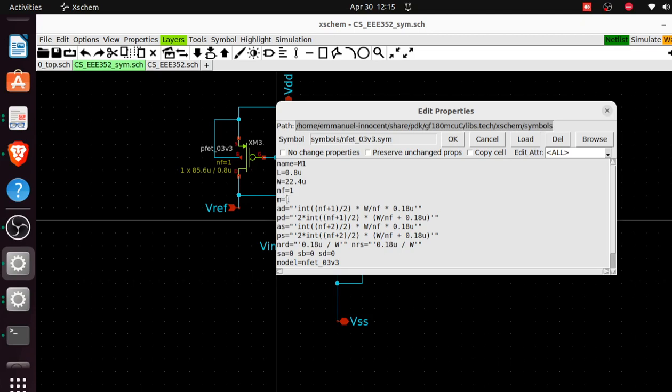So what we want to do about resizing the devices is turn them into equivalent devices with shorter width, but with more components. To do that, we can either use NF or multiplicity to achieve it, but they achieve that same thing in different ways. We can choose either.